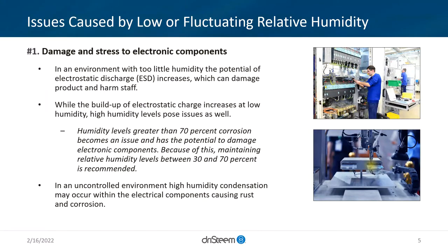So it's a really broad range. Just like that, human occupancy is different than the process range given. If we talk about human health, 40 to 60% RH, so now we're starting to narrow that scope. This is just one aspect of what that final RH percentage set point may be.